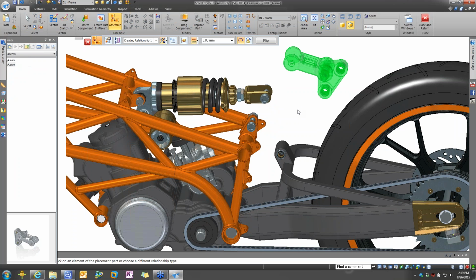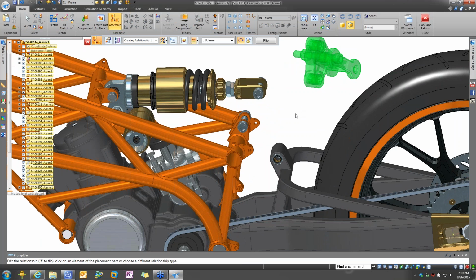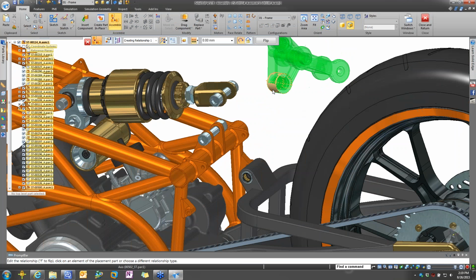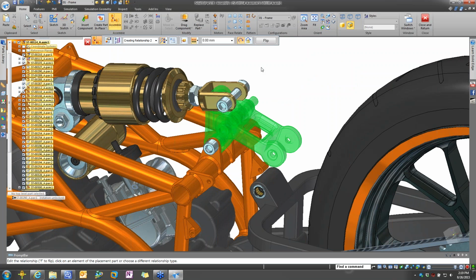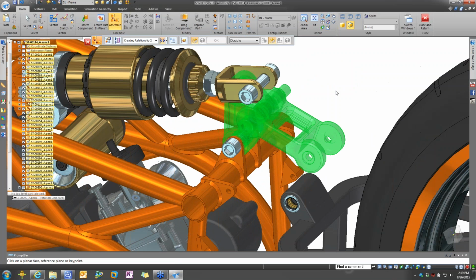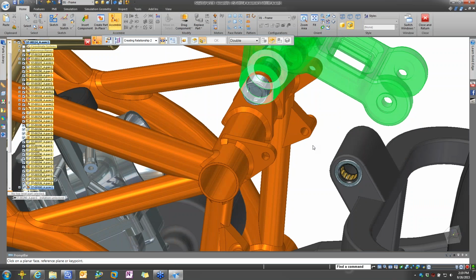And it's nice we can move these components around if we need to access specific geometry as we constrain. But in this case, I'm going to select the cylinder of our boss and just say let's align it to the screw. We'll do something similar to what we did earlier, where we want to keep that part centered. So we'll center these components relative to some of our supports on our frame, and we'll just easily select those.